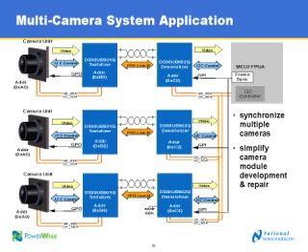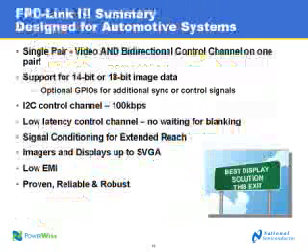That's right. Great. Okay. Another question that came in real fast. The question is, do we have a MUX solution or recommendation for multi-camera solutions if they want to select which camera stream comes over a single FPD-Link III cable? Well, I think that's kind of what we just talked about. The address remapping is really meant to replace the use of a MUX so that they can have the microcontroller talk directly to a single camera on a single link.